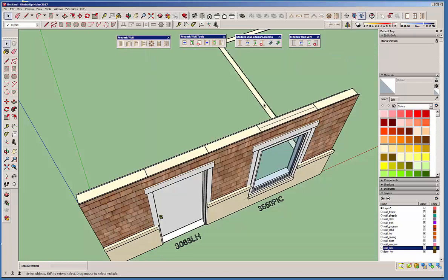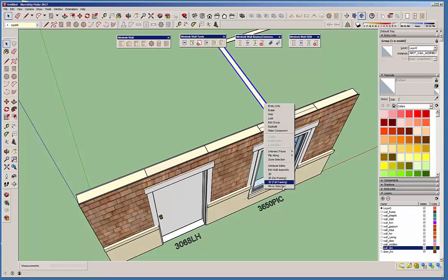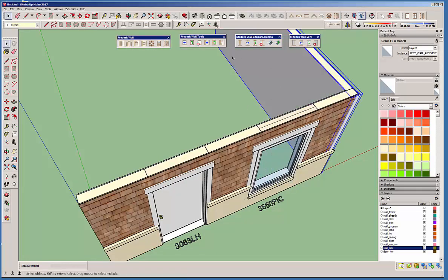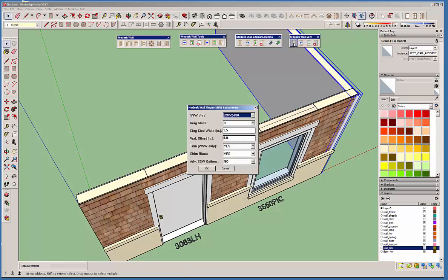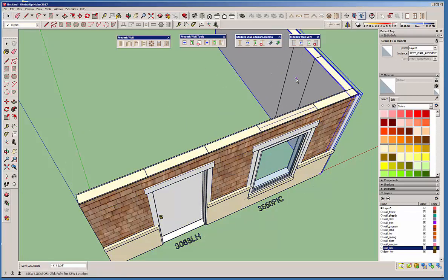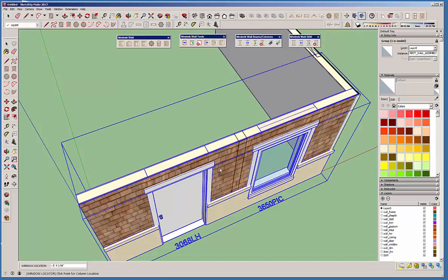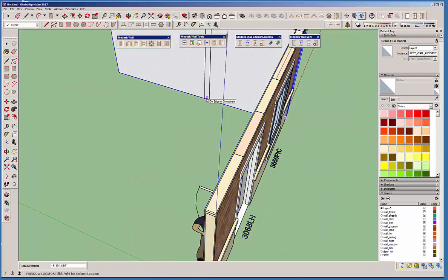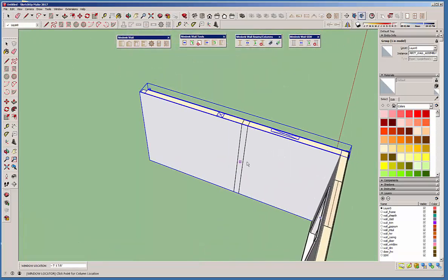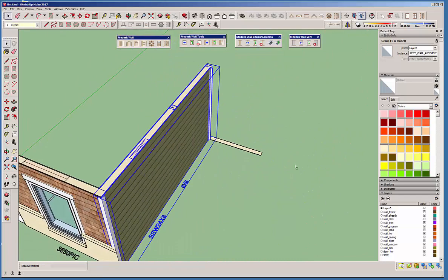I'm going to go ahead and bring this back up into 3D, and I'm going to drop just a shear panel there real quick, and I'm also going to drop in a wall column. Let me just move this over. Okay, let's go ahead and turn off the gypsum, and might as well turn off the insulation as well.